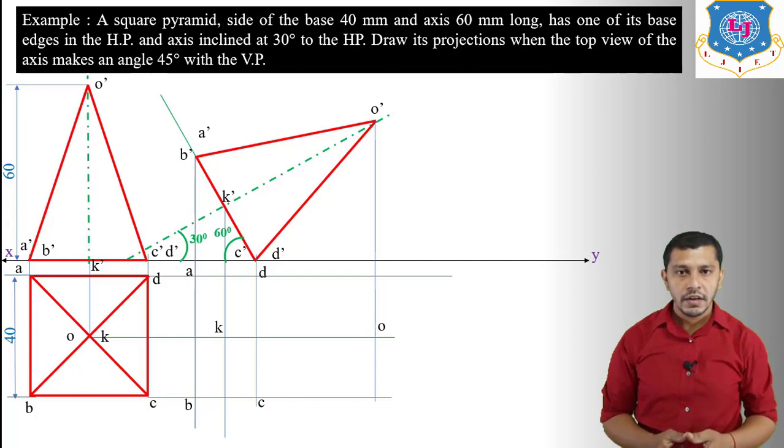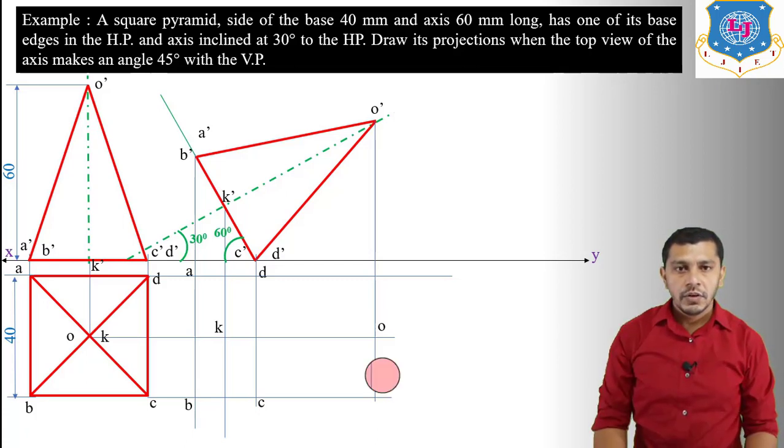And the third point that we will apply after drawing the visible part in the top view is two visible lines will never intersect and two hidden lines will never intersect. So if any edge is intersecting the visible line, it is going to be hidden in the top view.